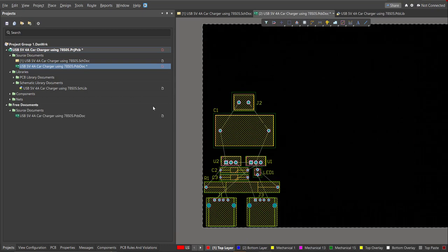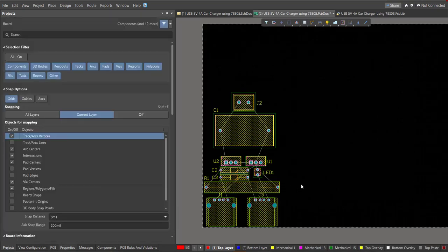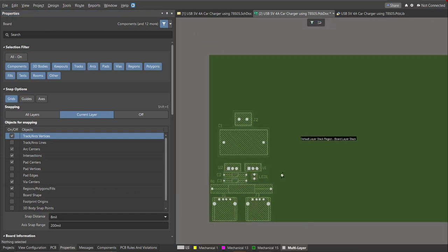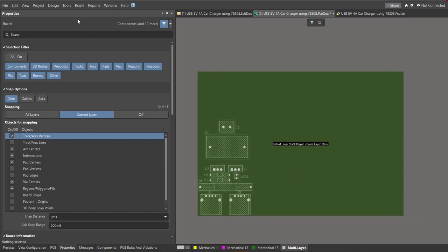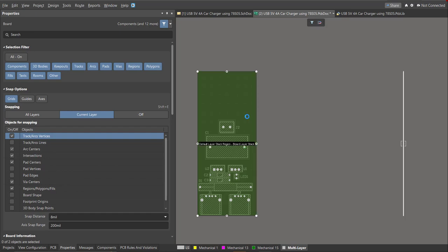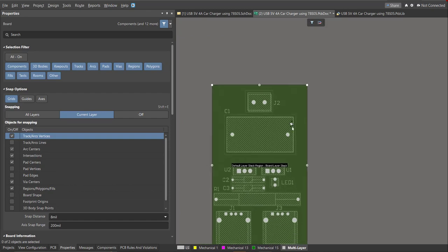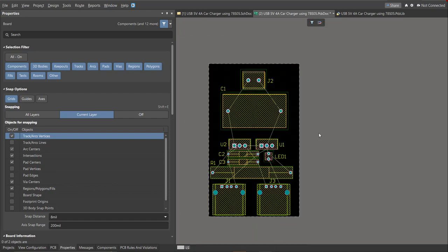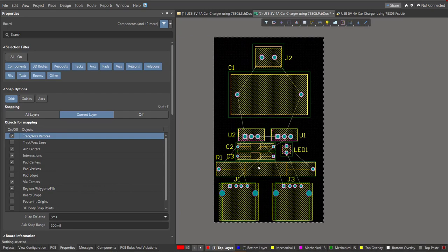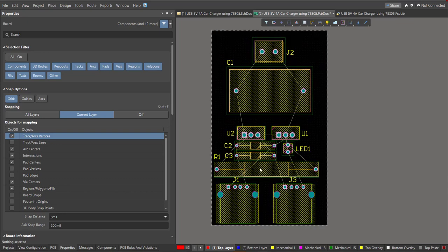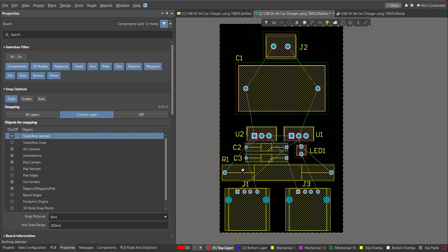After you place all the components inside the PCB, next we're going to edit the board shape. Just press 1 on your keyboard to activate this kind of view, then click on Design, then Edit Board Shape. Now the snap points will appear, so we're going to drag them manually in accordance with your board shape. Now press number 2 on your keyboard to go back to 2D view. As you can see, the board shape has been set. And now we can start with the layout.